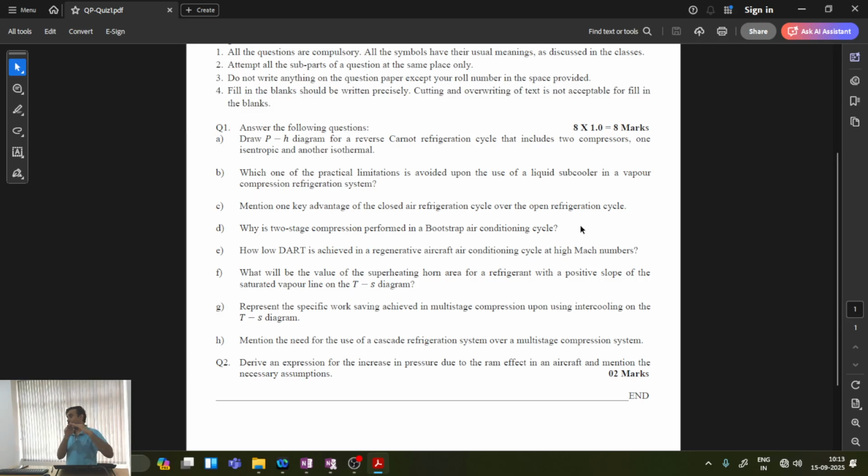So if it does not come to low temperature, then there are two possibilities: either use some external medium which can decrease the temperature, or increase the pressure to a higher value so that expansion takes place in the turbine across a large pressure ratio. If expansion takes place across a large pressure ratio, then we will have low temperatures at the exit. Shall I explain this?